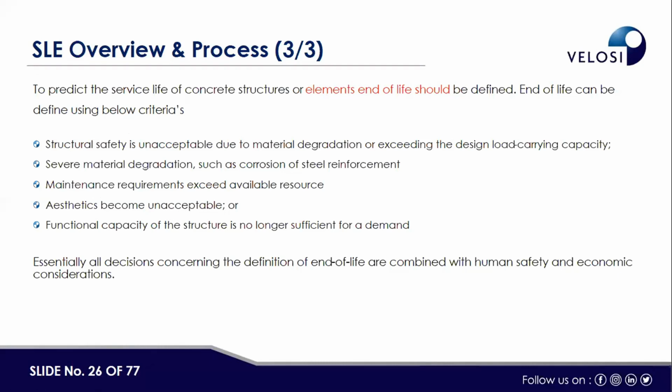However, in the UAE, especially in Abu Dhabi, many buildings are being demolished after 30-40 years. One of the reasons given to us is that Abu Dhabi is an island with sea around it, and the water table is high, which causes more corrosion to the piles and foundations, and that is normally a threat. The height of these buildings is more than 15 or 20 stories, so they feel there is a risk of failure, and that's why preventive measures are taken to demolish these buildings. However, if new technology like cathodic protection and other measures were taken, then the life of these buildings could be extended further.